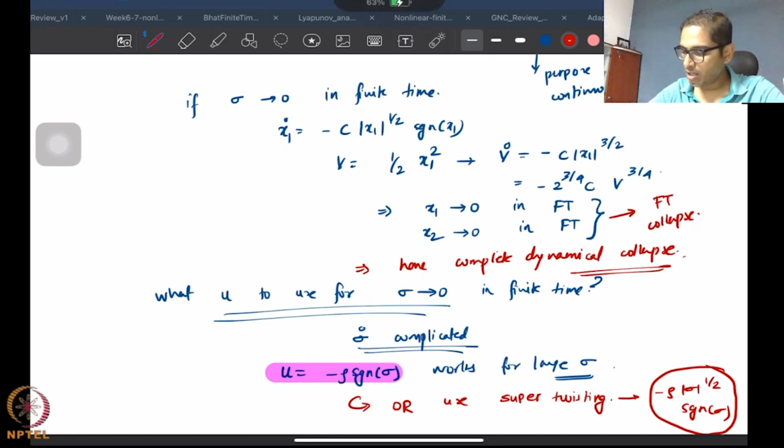All right. So that's all we wanted to discuss in sliding mode control. We did first order sliding mode, we did second order sliding mode. We understood how, using the notion of equivalent control, you can obtain the value of the disturbance itself. We understood the limitations, in the sense that there are uniform boundedness assumptions. We understood that there are chattering issues that we need to resolve.